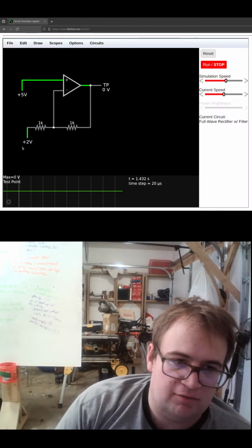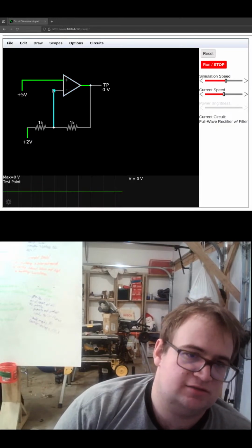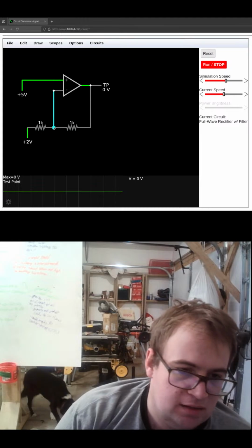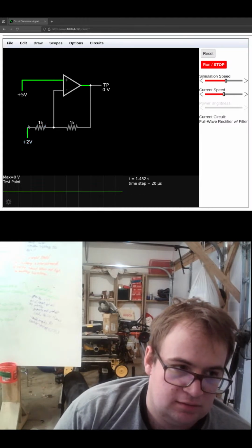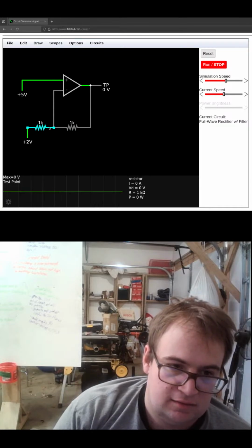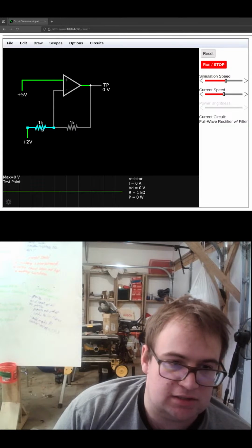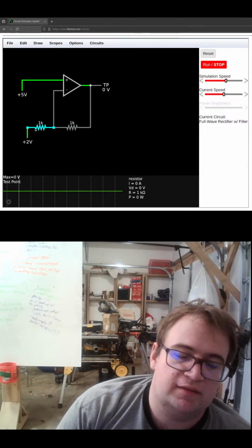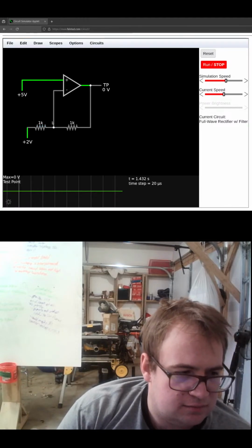Just trying to figure out how much. Well, here, that's the easiest way. So we know we would want to have 5 volts here. That means we must have gained 3 volts there. That means there must be some current moving this way, right?